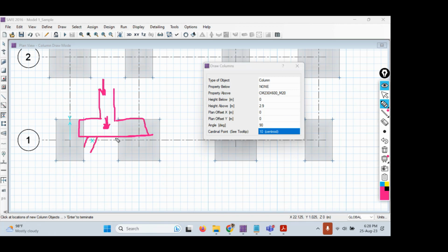Non-uniform settlement will happen underneath the foundation slab, so we don't need non-uniform settlement. In order to avoid the non-uniform settlement, we always should consider the centroid point. So let it be like this only, the default option, right?